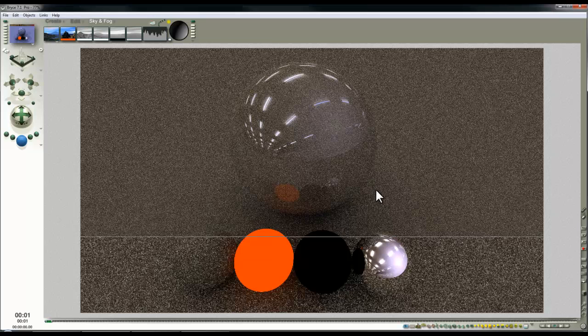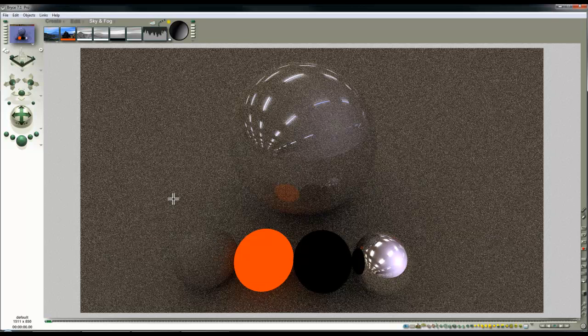What's happening is that the surface sends out probes into the environment. So we look at any pixel on the surface, and then probes are scattered out into the environment, looking out in all directions and seeing what light source is available. Now if this sees the background, or itself, or the ground, or this ambient sphere here, and through reflection and also through probing the environment still further up to the maximum ray depth, it determines how bright that pixel should be.